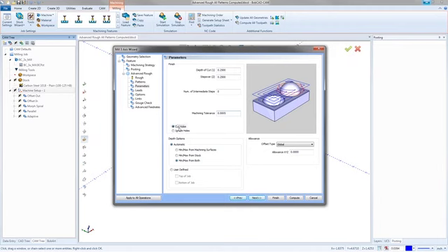Ignore holes, cut holes is just dependent on the geometry. And it really does depend on the geometry and how everything sits on whether this recognizes there's holes. The problem that you run into any time you're working with some of these 3-axis tool paths, especially the finish passes, is when you're using a ball mill. Where it gets down to the tip of the ball, it's very small, or it can be read as a very, very small diameter at the tip of a ball mill. And so when we see a hole, if the tool can fit, it's going to put it in and make a little cut and then move on. So sometimes, even if you say ignore holes, you'll see a little movement in the top of a hole and then it moves to another area.